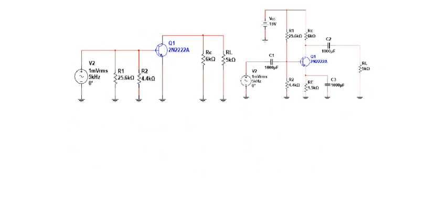All right, C1 got shorted out. Remember, all my caps get shorted and my VCC supply gets shorted. So VCC got shorted, that means RC goes to ground now. RC goes to ground. R1 also goes to ground. So R1 and R2 are now in parallel with each other and in parallel with the AC supply. RE was bypassed by C3, so it's gone completely. And then RC and RL are in parallel. C2 is shorted, VCC is shorted to ground, so I can turn the RC down and it's right beside the RL.